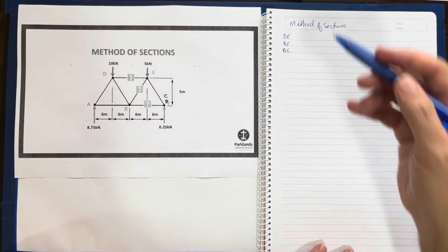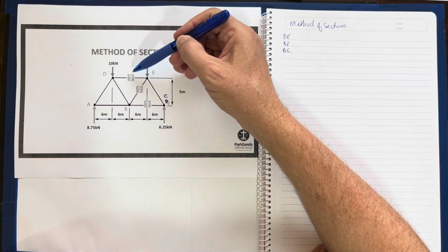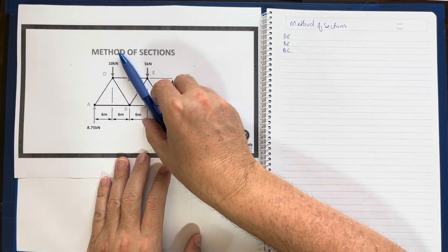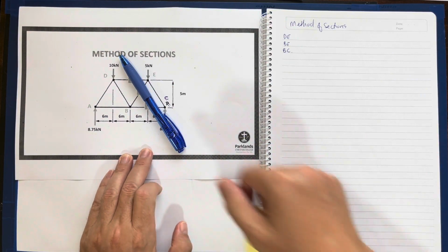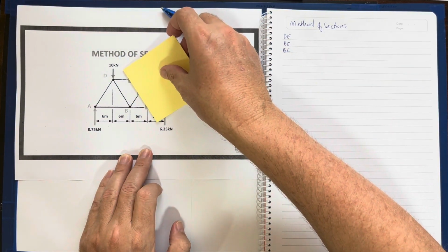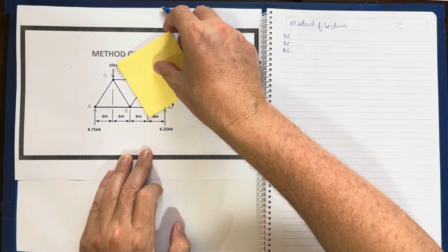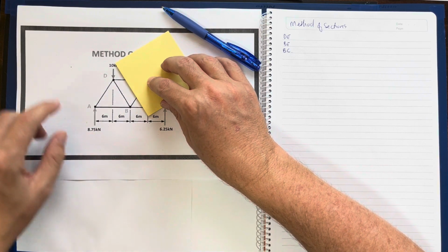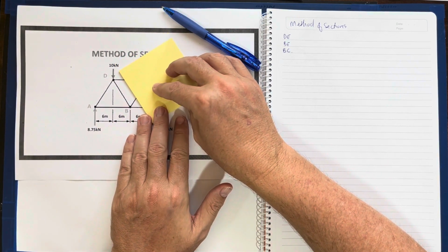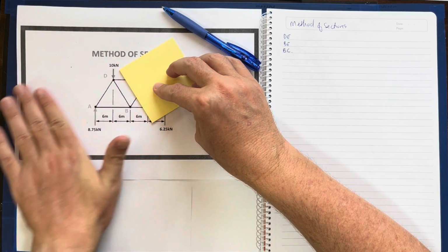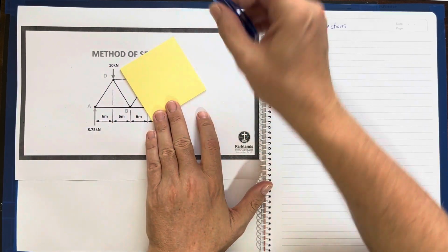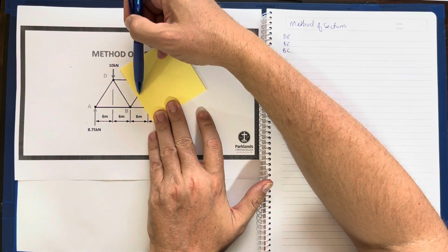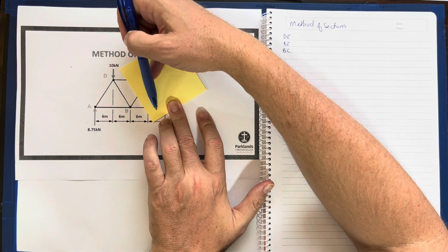So the technique is we take, like, scissors and we cut through this truss. I'm going to take my handy little post-it note, and we only work with the external forces on this truss that are on the left hand side, and we're only going to be working with D and whatever is left of E, B, and what's been left of it, BE and BC.